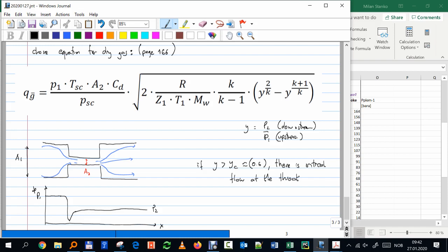there will be critical flow. At critical flow, if there is any pressure change downstream, normally it travels with the speed of sound all the way upstream. That means that if for some reason you have slugging or variations of pressure down here, they propagate with the velocity of sound, and you have them here too. So they will propagate upstream all through the system. But if you have critical flow, then the velocity of the fluid is very close to the velocity of sound. So any variation that I have in pressure here simply won't pass through the choke. You won't see anything upstream.